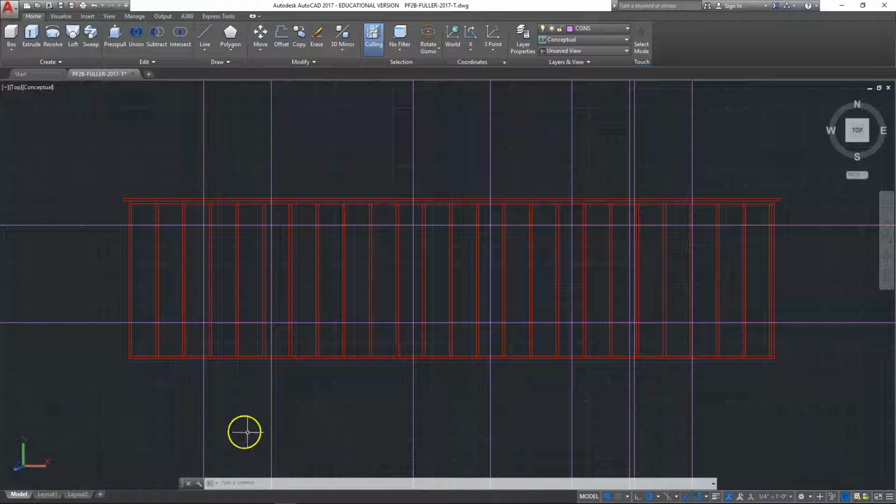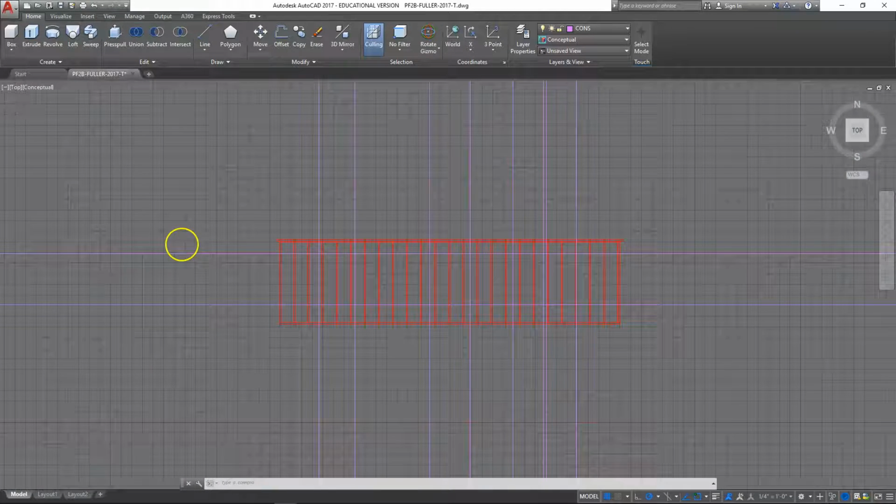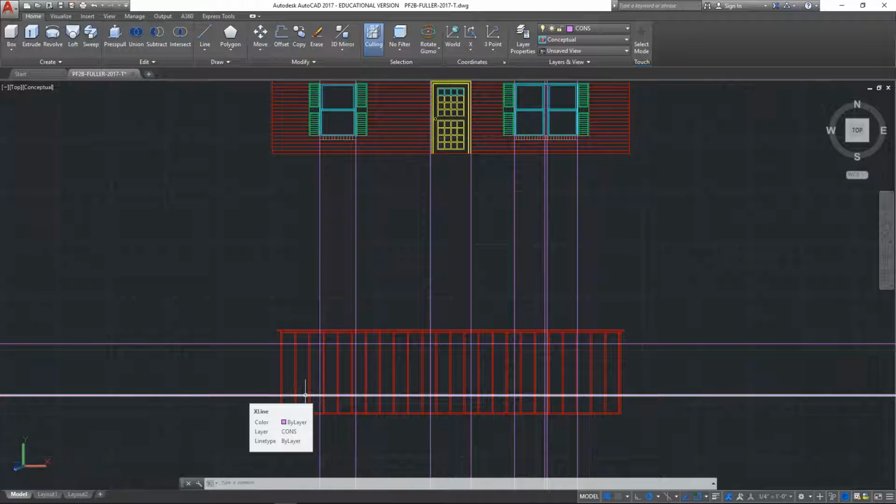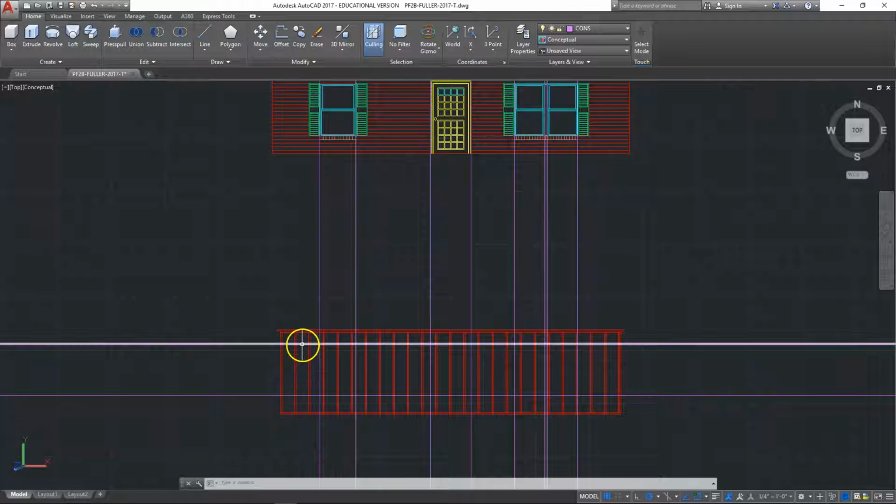With construction lines, mark the furthest outer edges of the windows and doors, such as I have already done. Place another construction line 6 foot 8 inches up from the bottom of the bottom sill. This marks my door and window height.